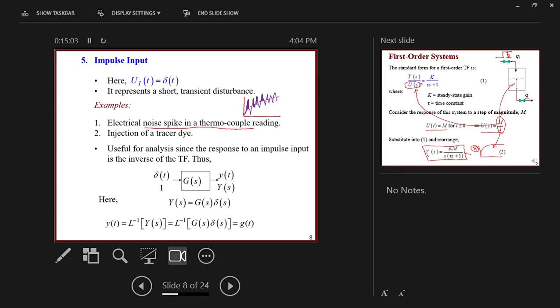So if we have, let's say, a reactor with a feed here and the output here. To study the mass transfer characteristics, we inject a tracer into the feed and monitor its concentration in the output. This injection process into the feed happens in a very short time, so we can approximate that as an impulse.